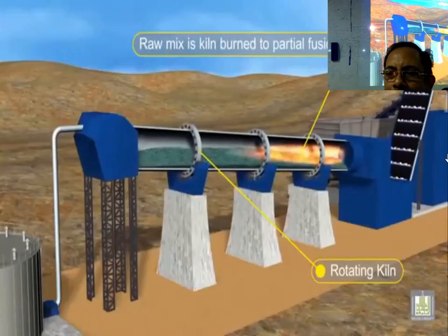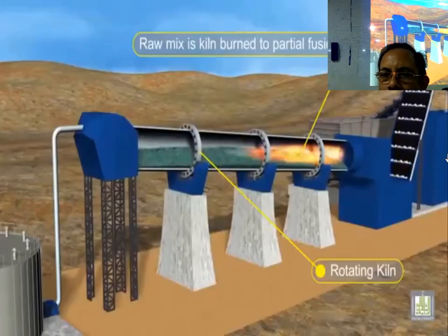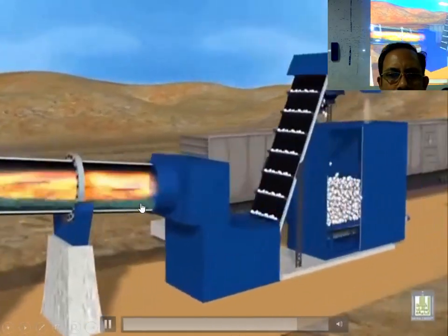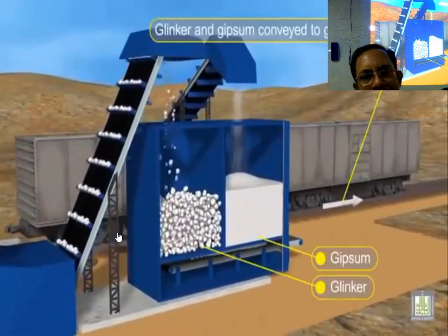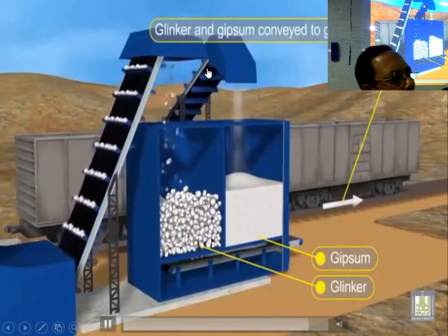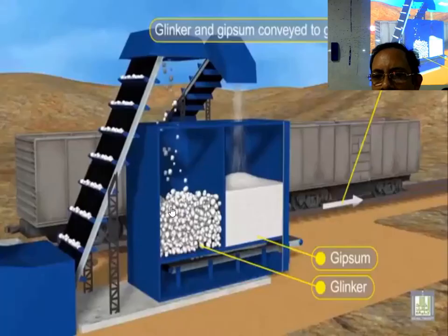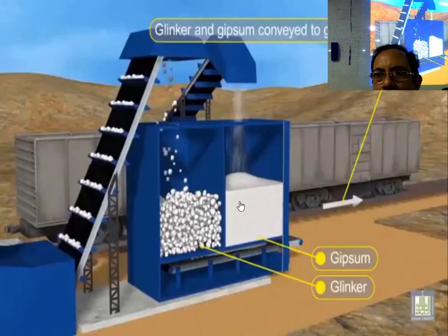The hot clinker is used to reheat the air for burning the coal, and the cold clinker is stored ready for use. The clinker is steadily ground with about 5% gypsum, which controls the setting characteristic of the cement. See, raw material is continuously coming, heating is done and collected. This goes up, and the whole thing is automatic. Then it is stored in silos, then carted for packing.